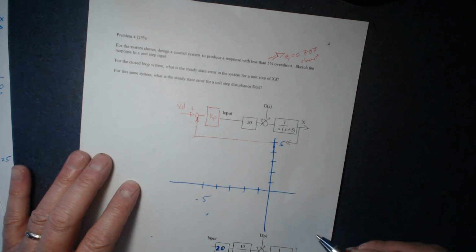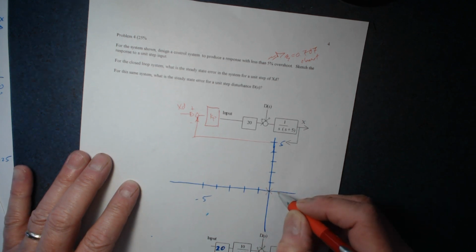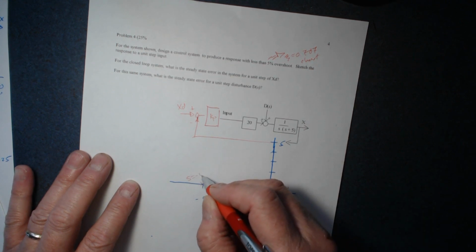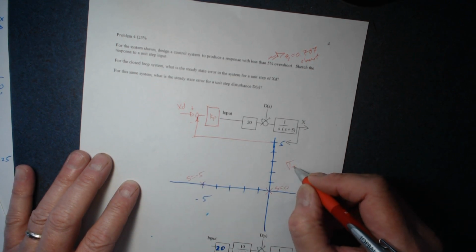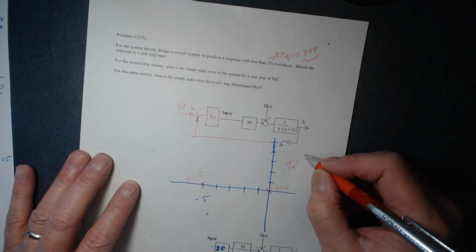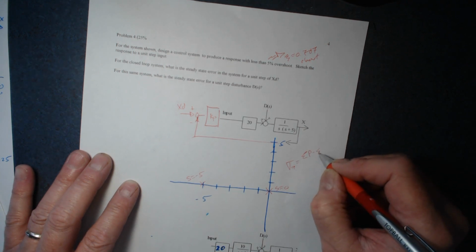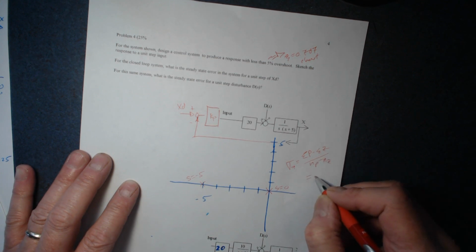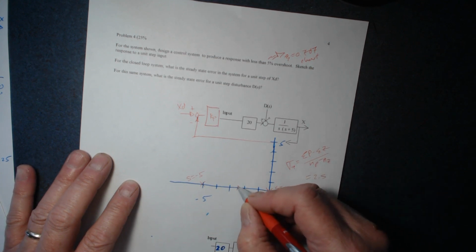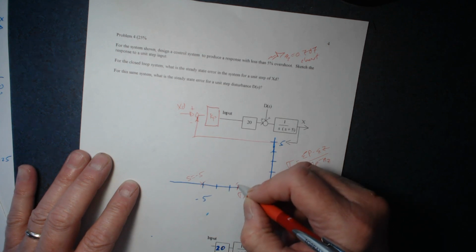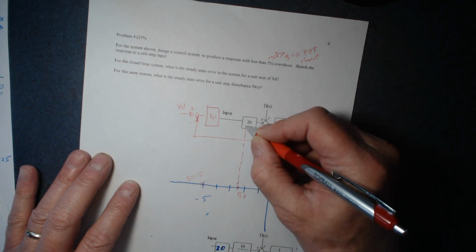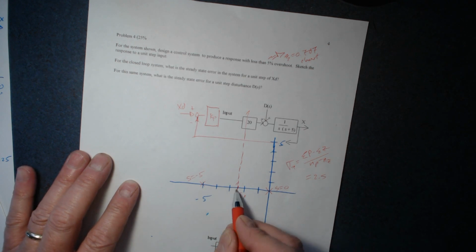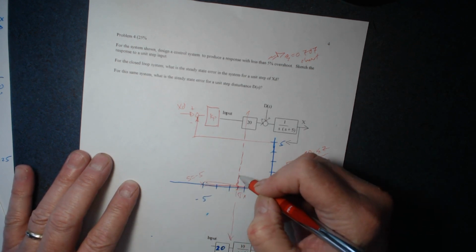Okay, and since I already know how root loci work, here's s equals 0, here's s equals minus 5, and I know that the sigma asymptotes is equal to the sum of the poles minus the sum of the zeros over number of poles minus number of zeros. That's going to be 2.5. So here's the breakaway point, sigma asymptotes. I know that the asymptotes are plus and minus 90 degrees, so I've got to write those in. So here's the root locus, right?